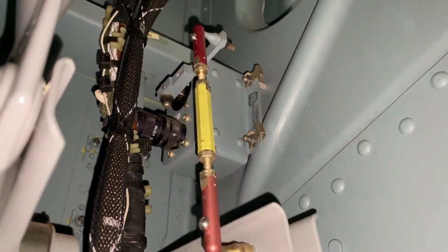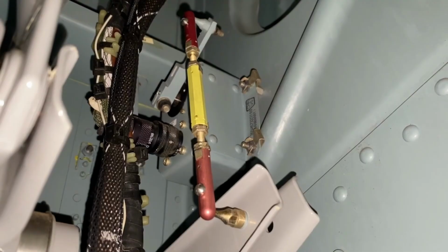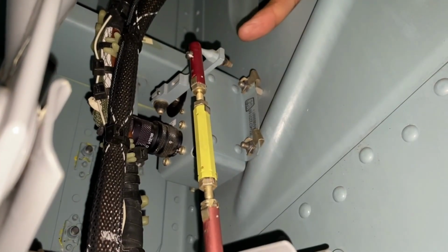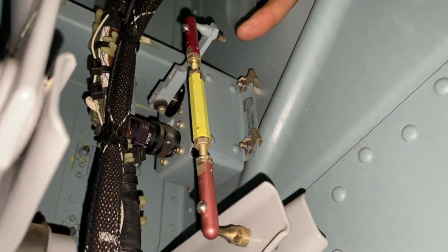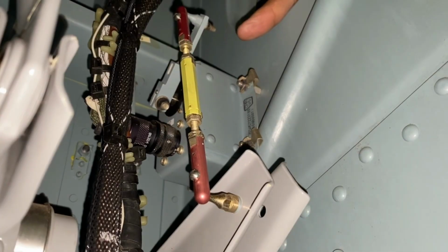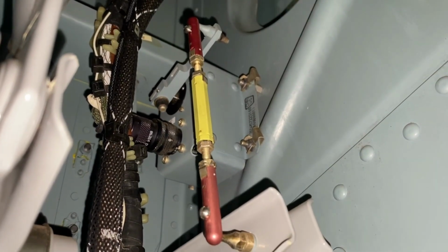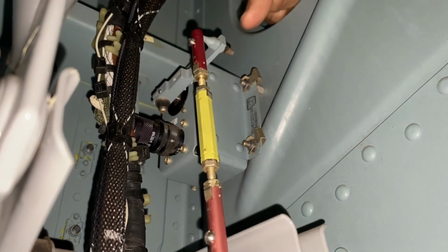Guys, this here is the XPC. It's right here, it's connected to the control chain. It's the one that sends the advanced signal to the FADEC system computer, to the DECU, Digital Electronic Control Unit. And it's a transmitter that has two channels. It's connected directly here to the control chain. Its adjustment is here. There's an adjustment.